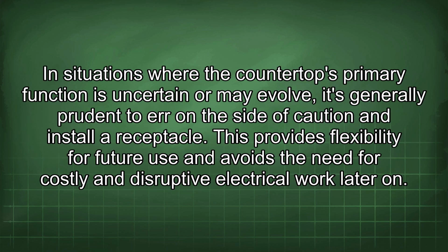In situations where the countertop's primary function is uncertain or may evolve, it's generally prudent to err on the side of caution and install a receptacle. This provides flexibility for future use and avoids the need for costly and disruptive electrical work later on.